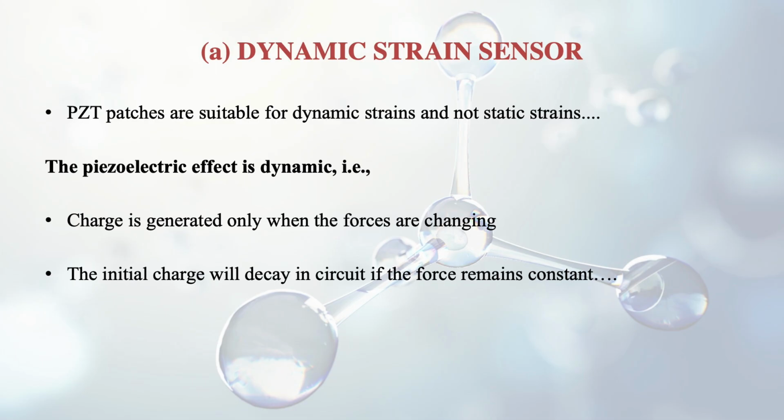Typically in the case of dynamic strains, we have found through our experiments that frequencies as low as 0.5 Hz can be easily measured by PZT patches. Now we are taking you inside our lab to show you the sensing application, that is the direct effect.